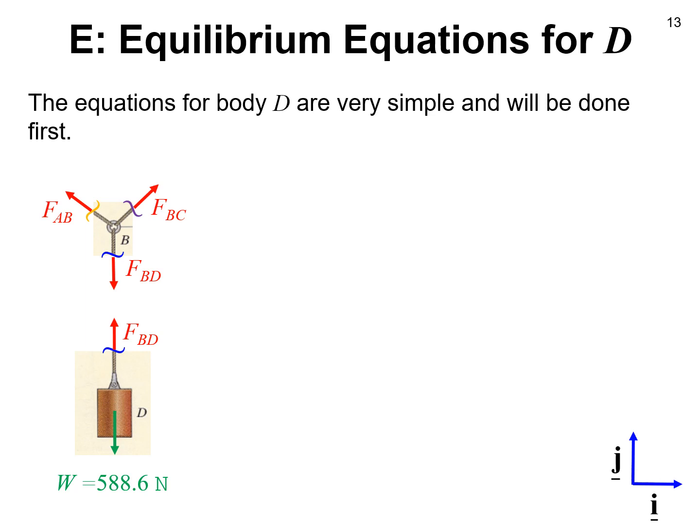Now in this case, let's say the cylinder D looks more simple to work with, and that's because everything is in the same direction, and we can guess that might be a simpler equation to write. So if I apply the principle, the sum of the forces equals 0, to the cylinder D, the only forces are in the J direction. So I have FBD times J minus W times J equals the 0 vector, which could then be written as 0I plus 0J.